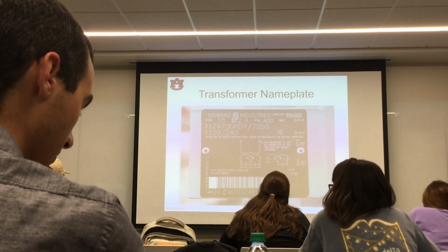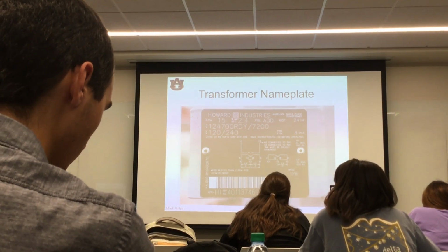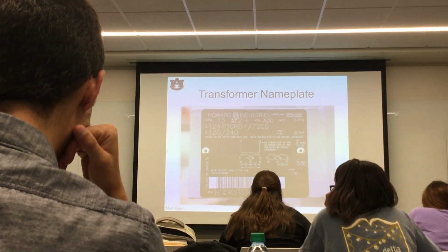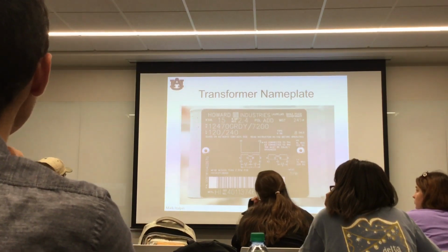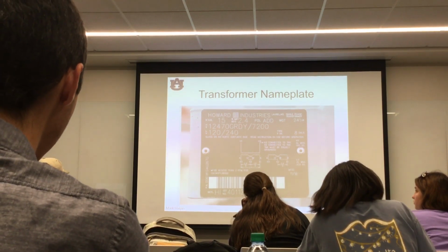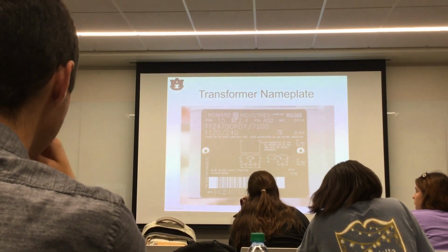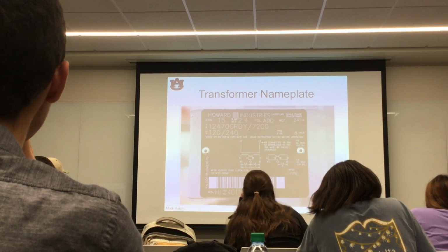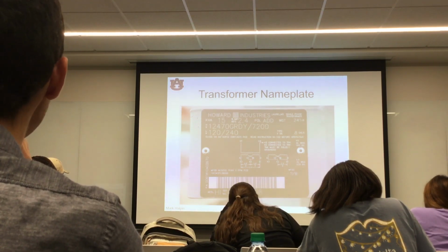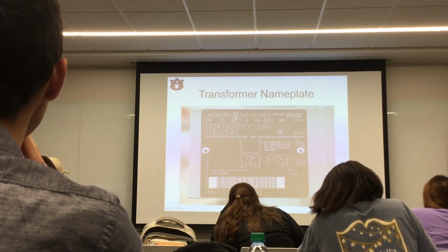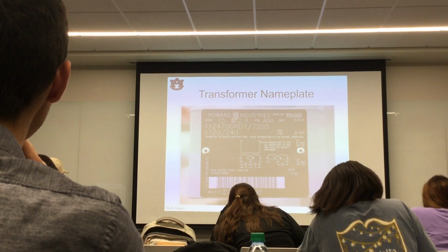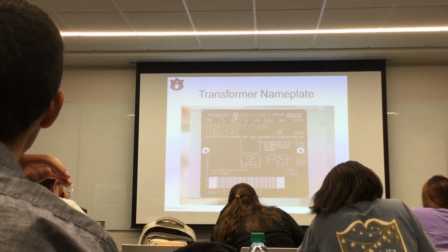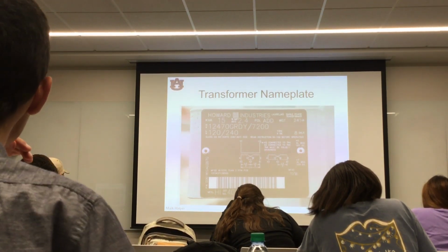Okay? When a manufacturer, in this case Howard Industries, gives us percentage information, the "of what" is always the ratings of the piece of equipment. Always. Okay? Remember I told you that in power applications, we pick two bases. And what two do we pick? We pick a voltage and a power. The manufacturer picked the voltage and the power. Alright?